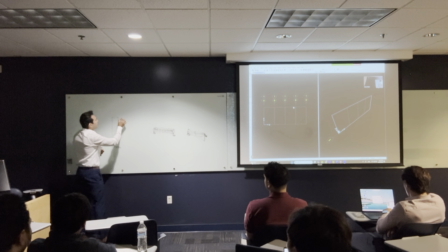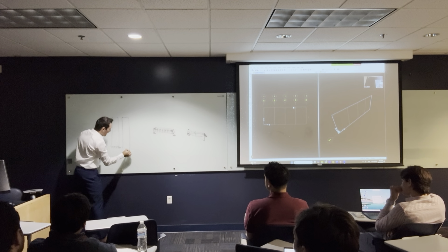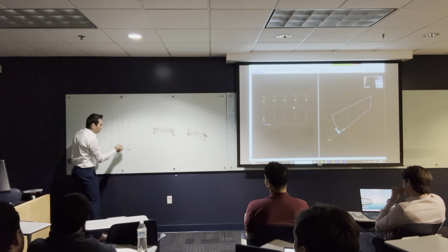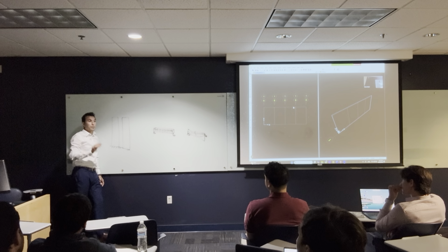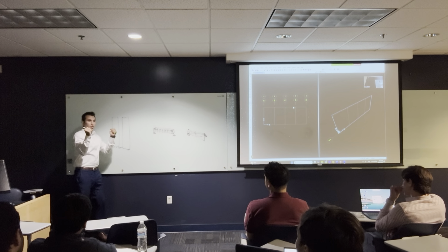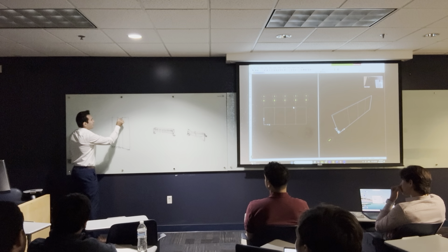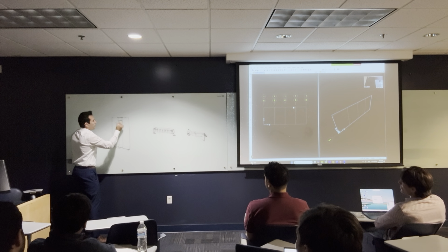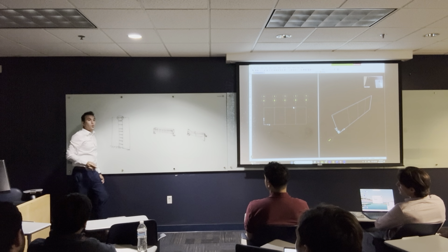But sometimes we end up having two shear walls with a space between them, and they are two separate shear walls. We make something called a coupling beam to make these shear walls act as one wall. Rather than each one moving separately, we make them feel like one wall. So we connect them with a beam at the story level, something like this. My master's thesis was on the analysis of this beam. This is called a coupling beam.